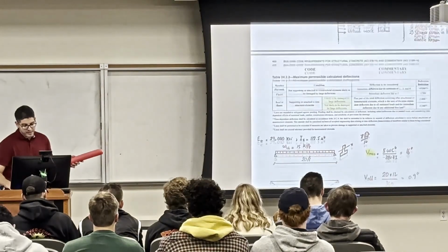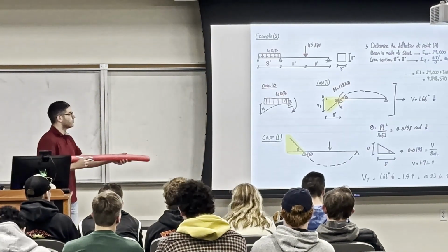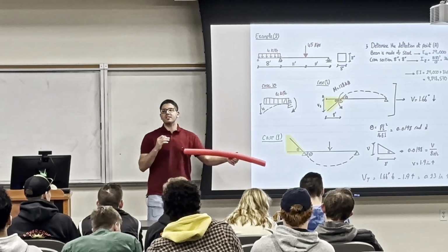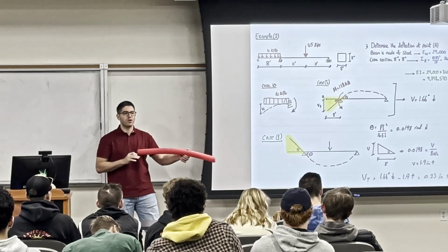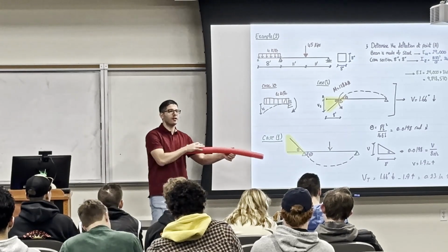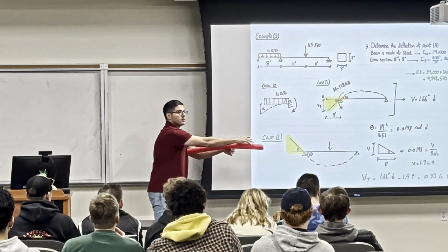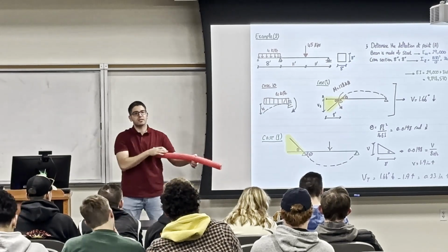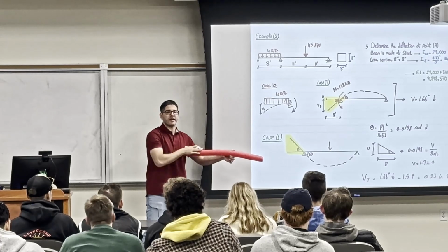So if you have a very large deflection, and it's unsafe in terms of deflection, not strength-wise, it's just deflection, some people would add a load in the middle of the span just to reduce the cantilever's deflection a little bit. And this load can be just a heavy dead load, like heavy flooring.